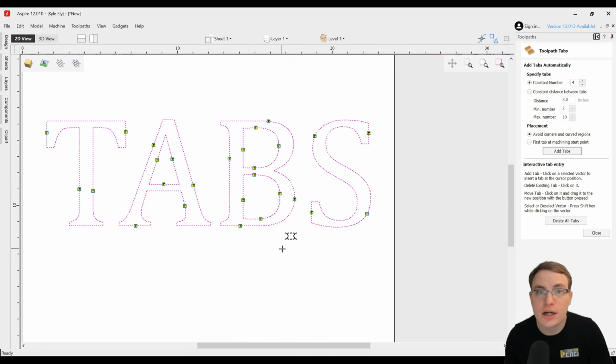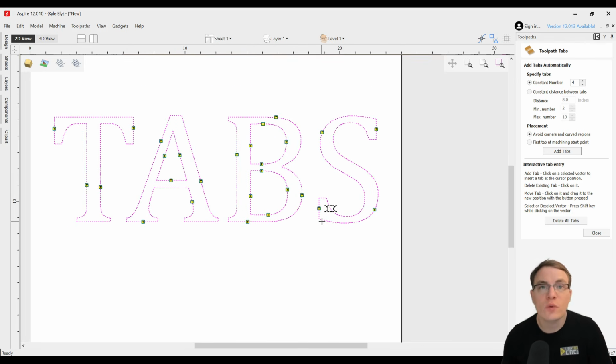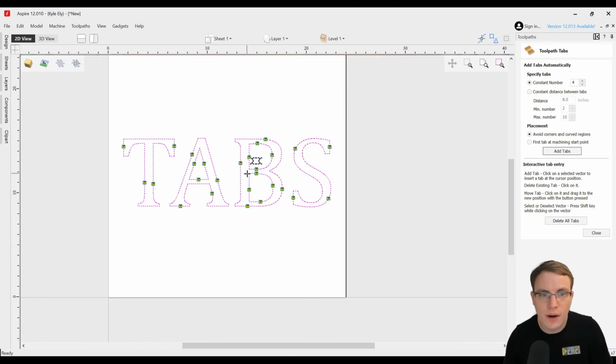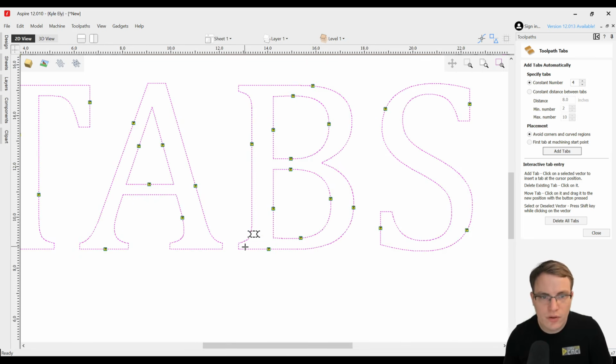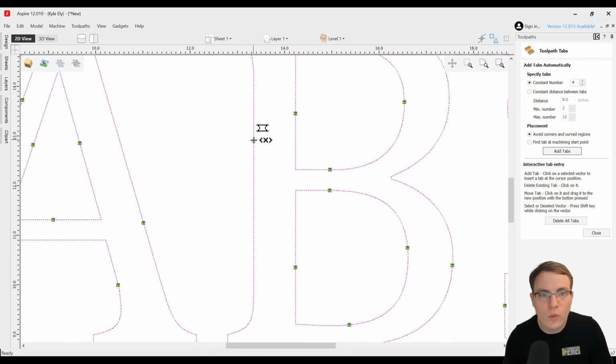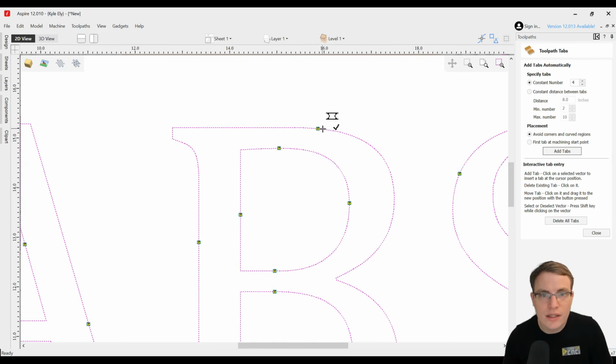Another thing I would mention about tabs is if you're working with solid wood, you have to pay attention to your grain direction. One solid wood in particular is oak or ash. Those are more of a porous grain, and I've actually had issues if I have the tab going with the grain. So for example, if the grain was going top to bottom in this example, this tab here would be weaker than a tab being on the end grain. So for example, one up here, that would be going across the grain.